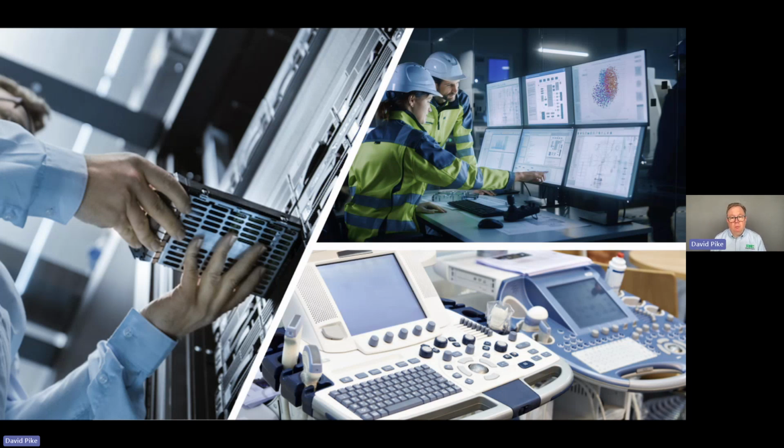And then at the bottom right, we have medical. Medical systems have, again, long used D-subs. The shielding provided by many of these connectors is imperative when you're talking about monitoring patients with very low signal levels from sensors either affixed to the patient or elsewhere. And so a shielded inline compact connector like the D-sub is very useful in that environment. And these very much are some of the traditional homes that you would expect to find D-subs.